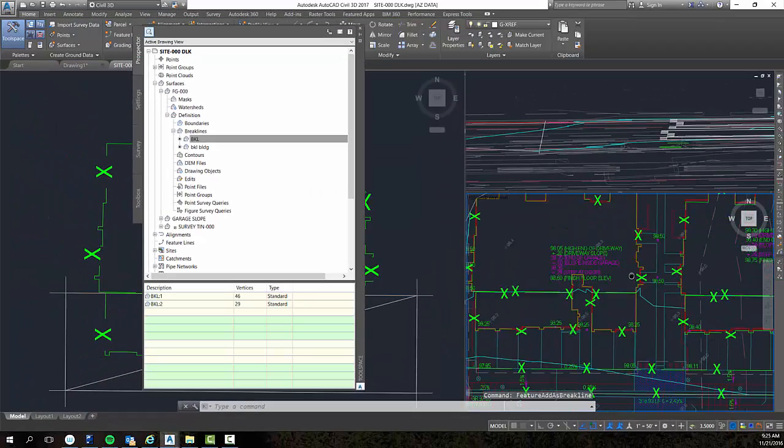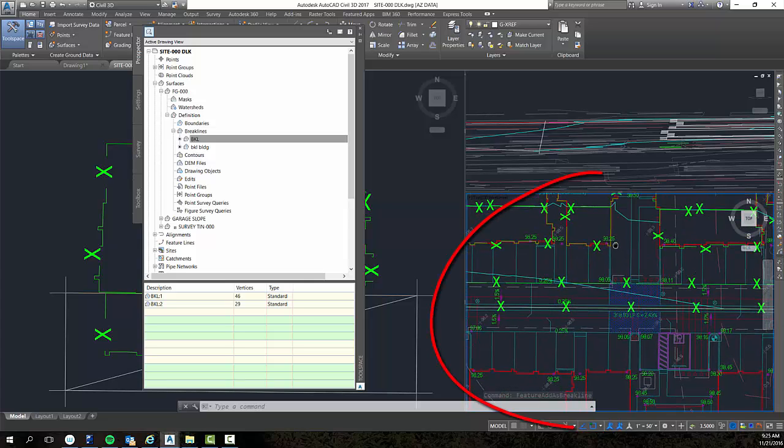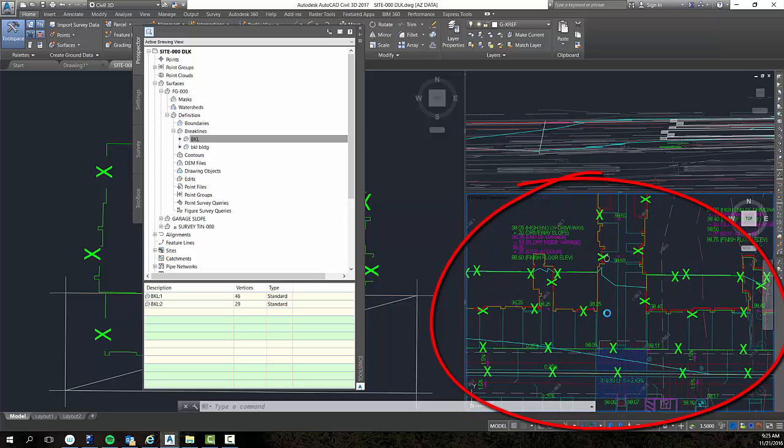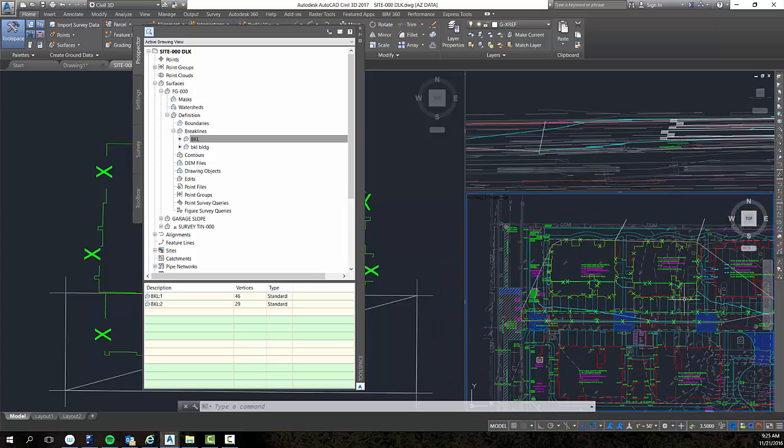And now you should see some contours starting to run from this gutter back in between the grades of the building, that sort of thing. So we're getting our buildings in there. We've got one side of our street in there from the gutter to the one side. Now we'll go ahead and draw in some more feature lines for gutter around the parking area, things like that. So let's go ahead and stage that up and get that going.